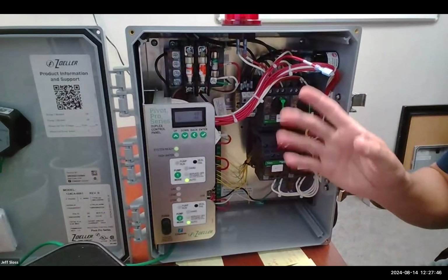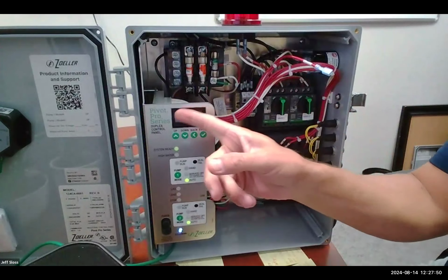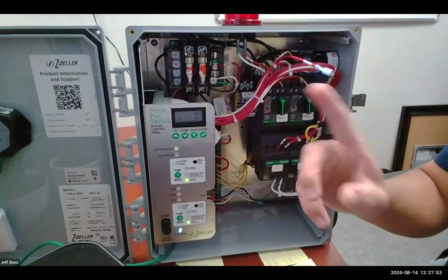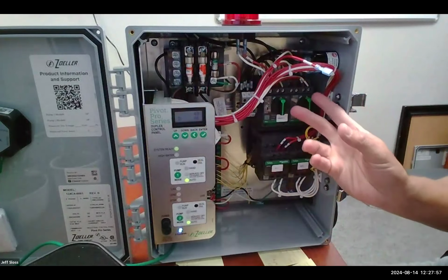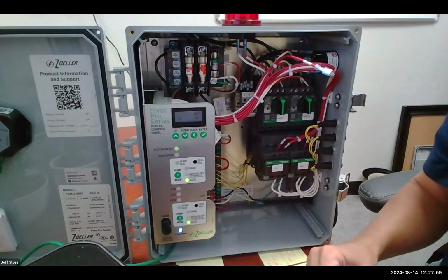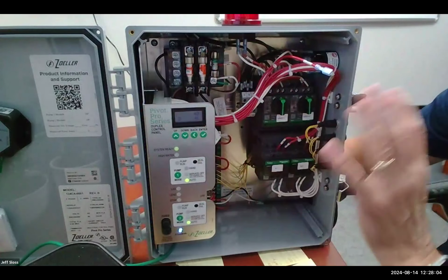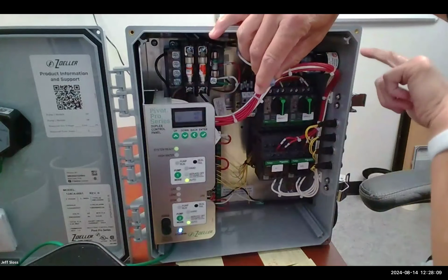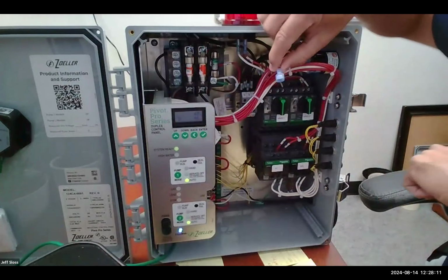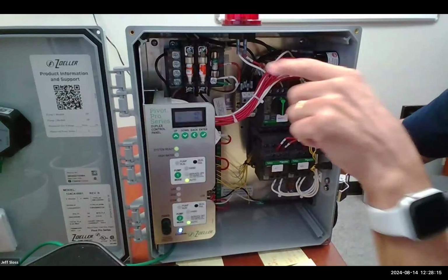panel here, so this is one of the 3-phase panels. This is a Pivot Pro, as you can tell, because it has a screen. We know it's 3-phase, by the way, because we can see a transformer up here, and we can see overloads here. That's kind of the telltale signs of a 3-phase panel. We make Pivot Pro in single phase also, but this one's 3-phase. I'll point out that I have my horn, my alarm out here. It's not wired, so it won't scare me. You don't want it going off. Make me jump.